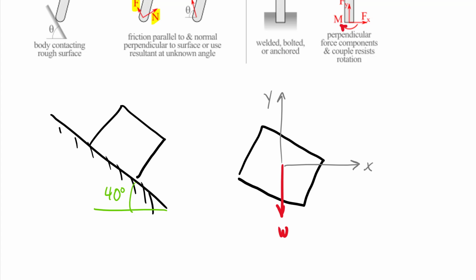My normal force here is going to be up this direction, perpendicular to that surface. And we'll assume in this case we add a force onto here, call this force P, make it parallel to the surface. I needed that force in order to make this plausibly in equilibrium. Given the normal force and the weight force alone, I would have had to add in friction or something to get me into equilibrium. But my question is, what is this angle here?